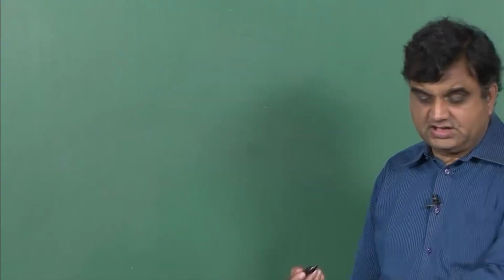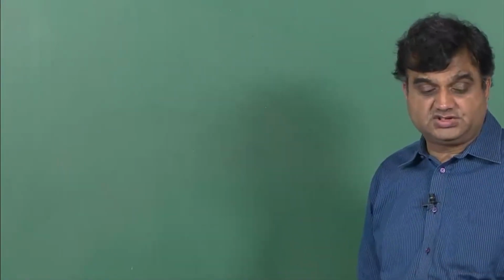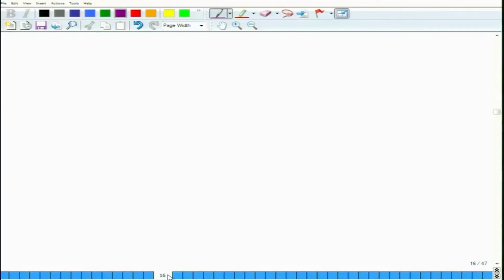independent elastic constants for such a material, and those are EL, that is the elastic modulus of the material in the longitudinal direction, ET, which is modulus of the material in transverse direction, the shear modulus GLT, and the Poisson's ratio nu LT, which is major Poisson's ratio. So, now what we will do is we will quickly do an example and then we will move on to the case of general orthotropy.